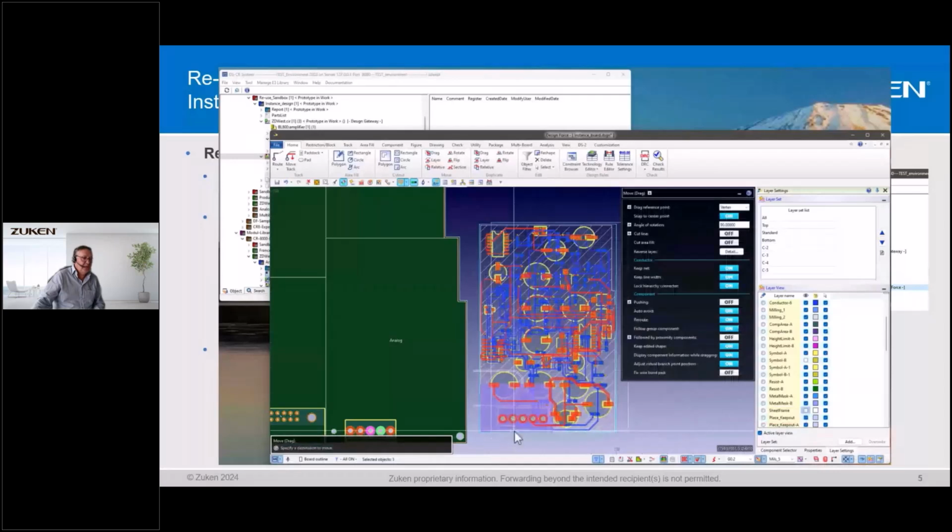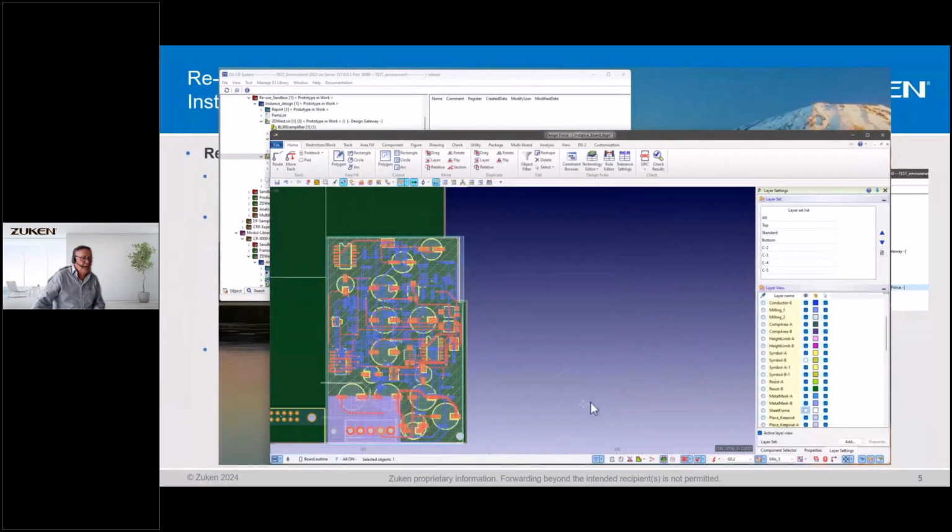Additionally, I snap to the center point of the connector pin and put this on that position, and it's going to be placed. But still at that point, these are only more or less the placeholder of the component position. These are still the module reference components. With the expand functionality, I now get the components from the arrangement location onto the module positions.